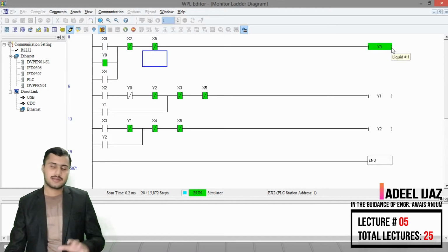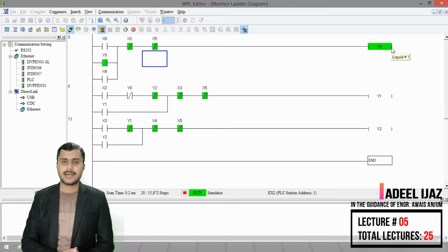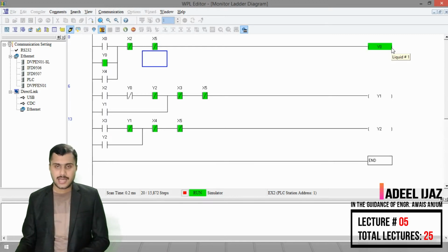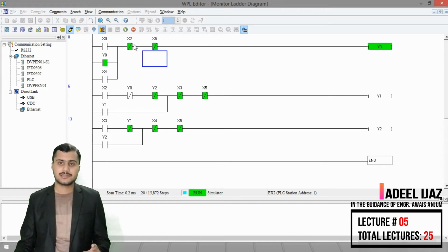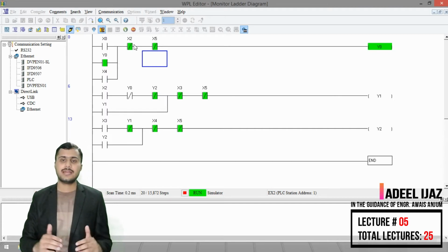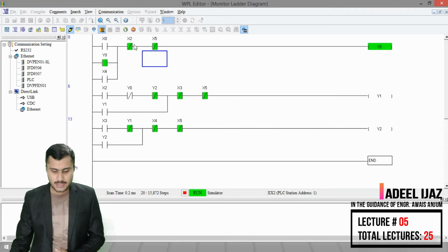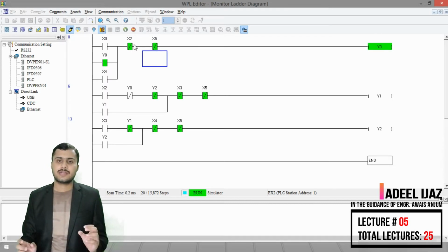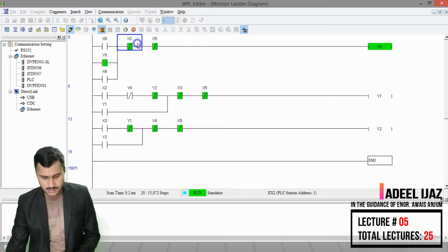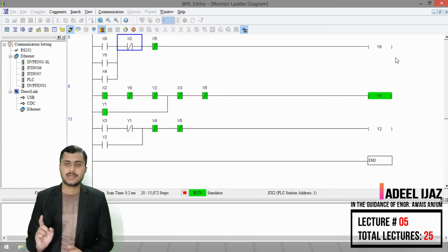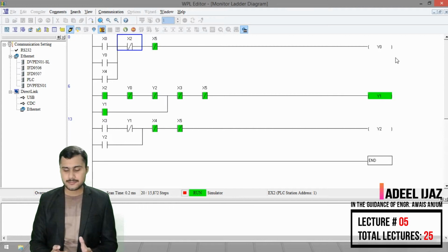Now you can see that liquid number 1 is entering into the tank, and it will enter until our X2, which is our sensor number 2, is activated. It means liquid number 1 stops entering into the tank when it reaches the level of sensor number 2. So let's say that liquid number 1 reaches the level of sensor 2. Sensor 2 will be activated, and you can see that our liquid number 1, which is denoted by Y0, is now stopped, and at the same time our Y1, which is our liquid number 2, starts entering into the tank.